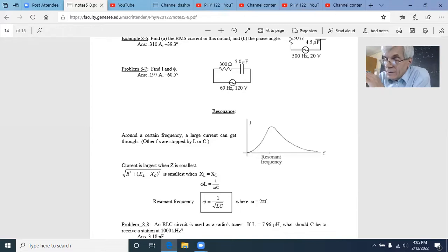On the high end, the current doesn't want to go through the coil. What opposes current flowing through a coil is the self-induced EMF. The self-induced EMF depends on the rate that the magnetic flux through it is changing, which depends on the rate the current producing that flux is changing.